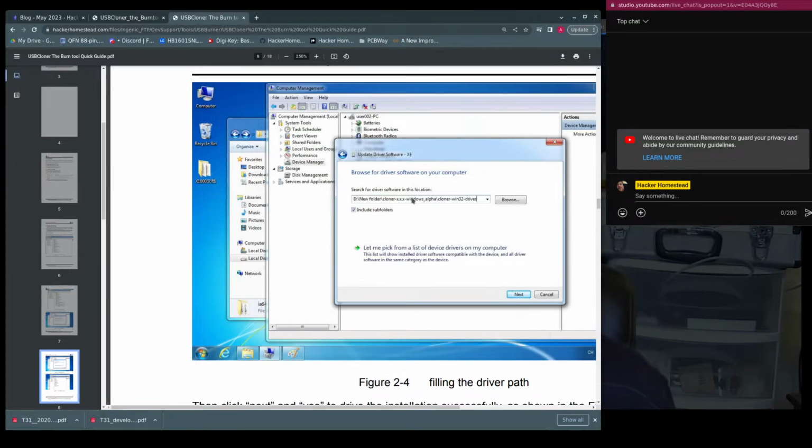Number one, when you go to install the drivers, what will happen is you'll plug in your device, and if it fails to boot in all other cases, such as SPI and SD card, it will go into a mode that is for USB flashing.